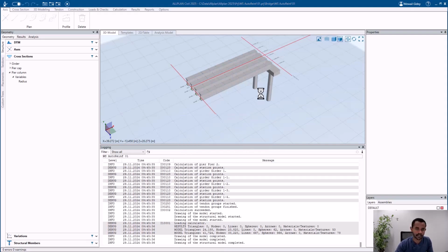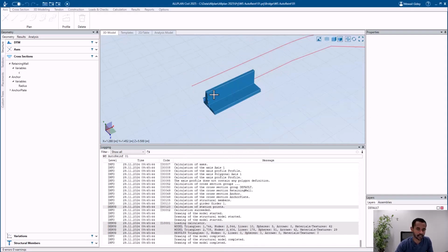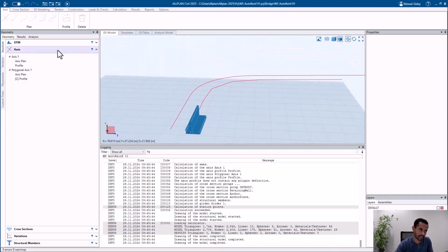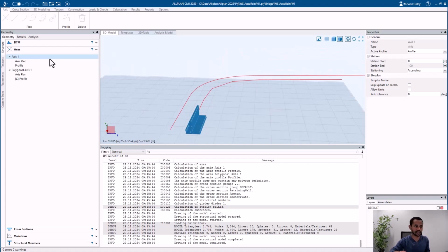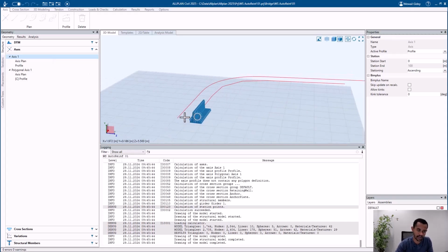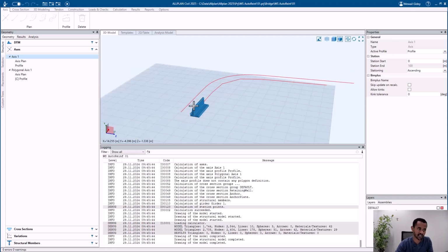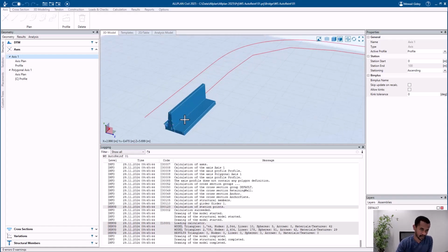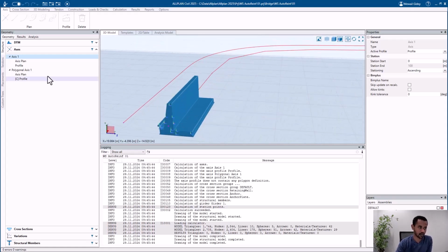We could have the retaining wall here defined, as you can see, and for this one I'm also using a normal axis. This axis could come through Beam Plus as a LandXML, or you could import it through other formats as well. From this axis I'm creating a polygonal axis, which allows me to polygonize the main axis that I imported. Based on that, I have here a retaining wall.